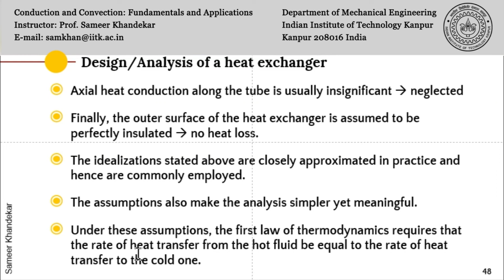So under these assumptions, let us apply the first law of thermodynamics. Essentially what it requires is that the heat transfer from the hot fluid is equal to the rate of heat transfer to the cold one, because these are the only two elements which are exchanging heat with each other. So this is done in slide number 49.